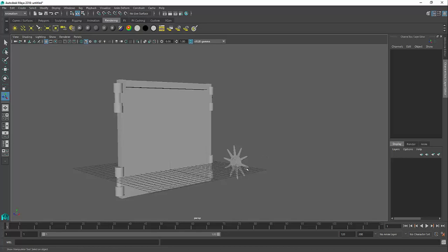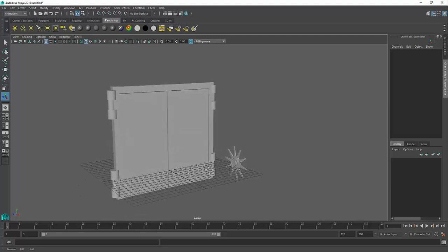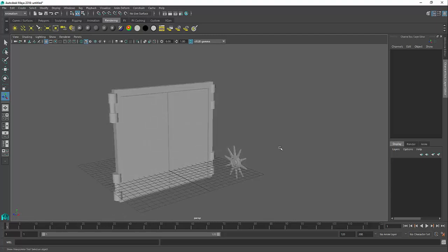As you can see in my scene, it's a very basic scene, and I'm going to use a very popular and important tool in Maya when it comes to rigging and animation. It's called the set driven key. The name itself says driven key. Since the menu set in Maya says Set, then Driven Key, people call it set driven key. Sometimes people refer to it as SDK. Not software development kit. When animators say it, they mean set driven key, SDK.